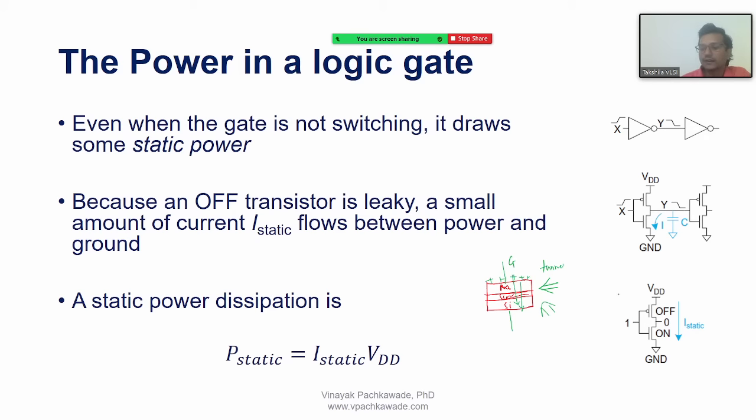So look here, I have a logic 1 applied and the output of the inverter circuit is logic 0. When I apply logic 1, the NMOS in the bottom pull-down network is on, but the pull-up network is obviously off, right? So this circuit can be represented with VDD and this PMOS, which is switched off, and this is the output right here. But there is a static current I'm getting here from VDD to the ground. Why?